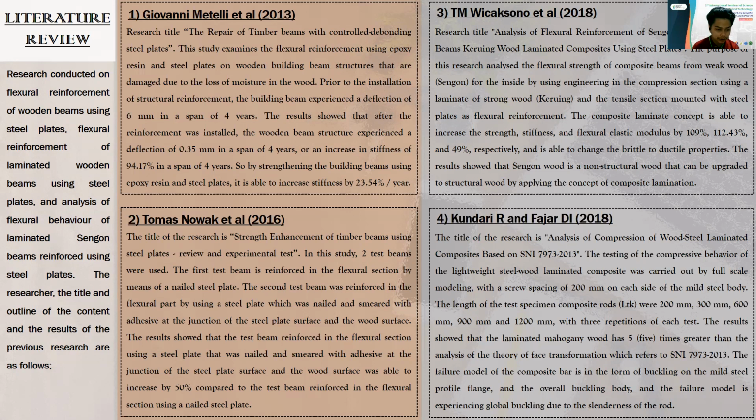The title of the research is The Strength and Tension of Timber Beam Using Steel Plates, Review and Experimental Test. In this study, two test beams were used. The first test beam is reinforced in the flexural section by means of a nailed steel plate, and the second test beam was reinforced in the flexural part by using a steel plate which was nailed and smeared with adhesive at the junction of the steel plate surface and the wood surface.